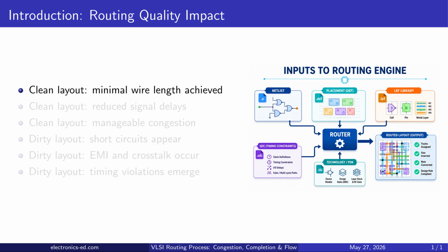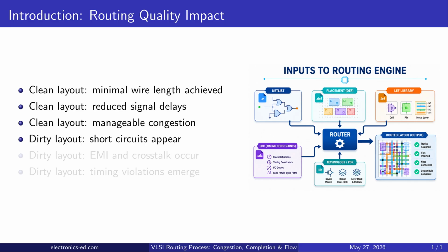A clean layout achieves minimal wire length. It also delivers reduced signal delays. And it keeps congestion manageable. A dirty layout, however, leads to short circuits. It also causes EMI and crosstalk between signals. And it makes timing violations emerge, hurting performance.